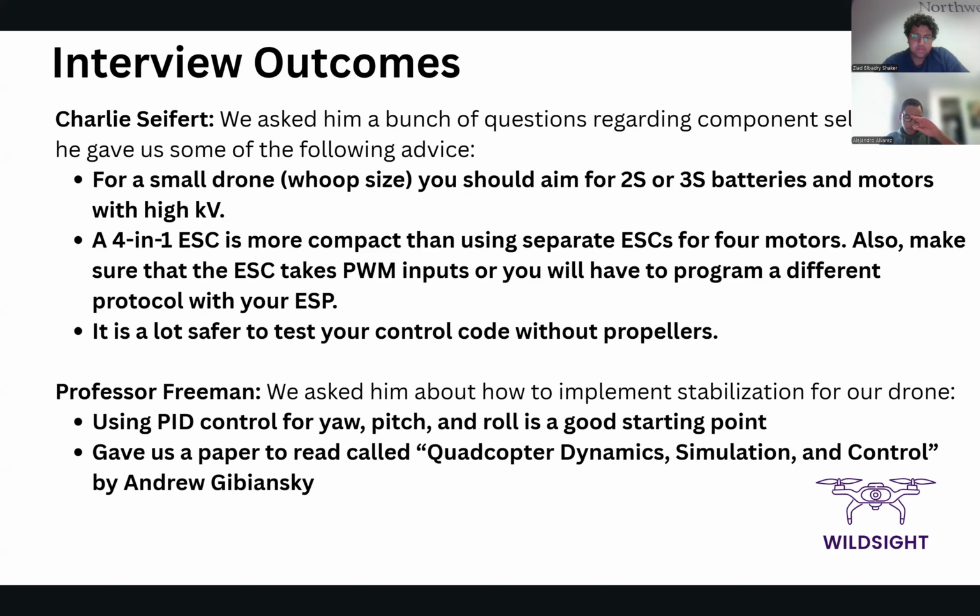Charlie also told us about the 4-in-1 ESC he used, but he also told us to make sure it takes PWM inputs, because the mistake he made was that his did not, which means that he had to program a different protocol to communicate to his ESC from his ESP32, called DShot, which is something we could implement in our project, but that's not really something we have time for at the moment.